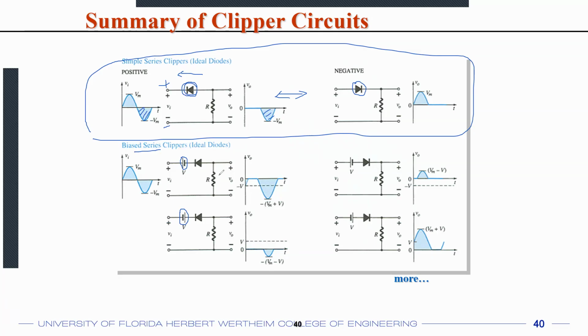So again, you can do the calculation in a graphical manner. You can do the calculation using numbers. But what you end up with is that when the diode conducts, do I add a voltage or do I subtract a voltage from it? Right. So for example, when this diode conducts, that means the positive is on this side, the negative is on this side, which will only happen in the negative half cycle. But in that case, you have the battery connected with the negative side here and the positive side on the left side, which means that you're adding the voltages in series.